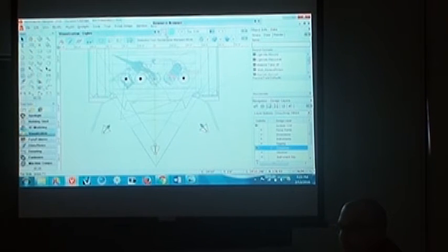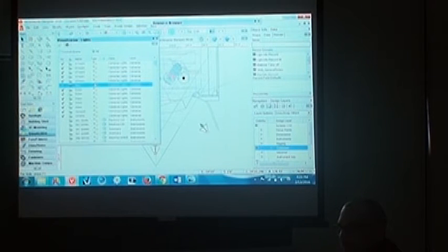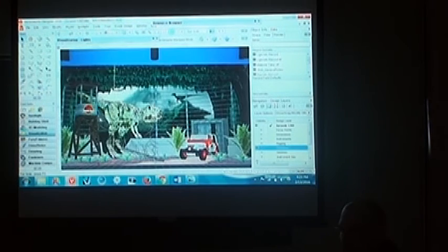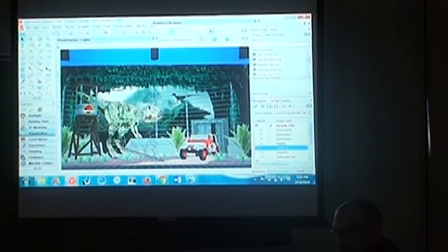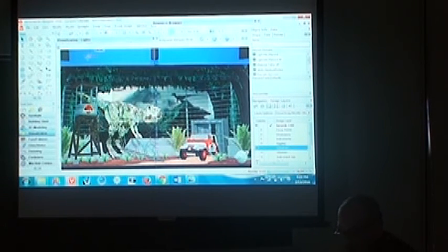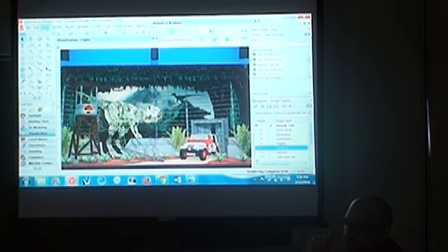And I'm going to go to a front view here. Front. And I'm going to go to rendering, custom RenderWorks. Using the custom setting and controlling the quality there lets you get somewhat realistic renderings without wasting the time of a final quality until you're ready to do that. You can see we're already starting to see some realistic stuff here. You can see shadows from the light sources out front.